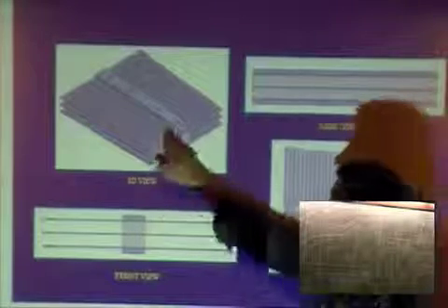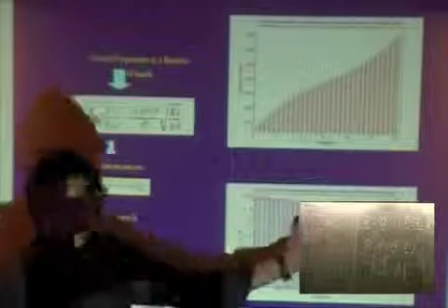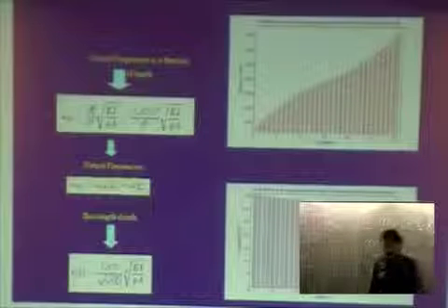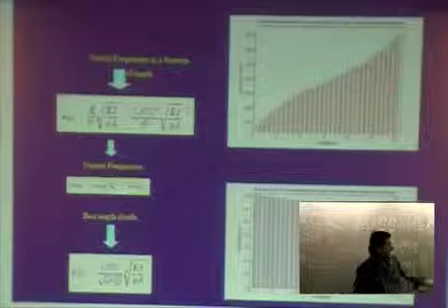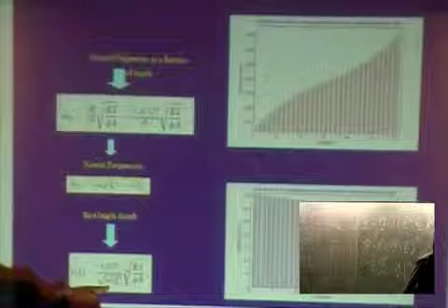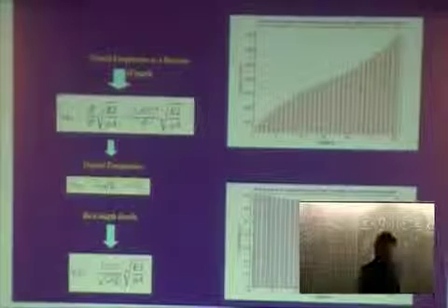So what about the lengths of these beams? Of course, we can select the frequencies from this curve. So we selected 180 resonators. They are 60 for each layer, so 30 for each layer and for each side. Then we selected from the frequency distribution the length using the beam theory, so it is very easy. And then you have a distribution of lengths corresponding to the distribution of frequency that you want to realize.